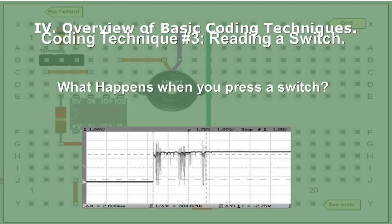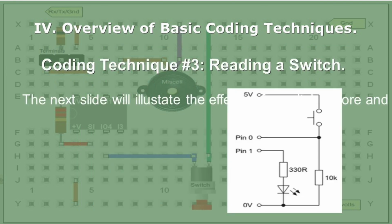Now, we talked about debounce. What happens when you press the switch? That's what happens. That's about typical for a press switch. Each one of those bounces will count as a switch contact. It's horrible. There are 2 ways you can do it. You could do it in hardware, or you can do it in software.